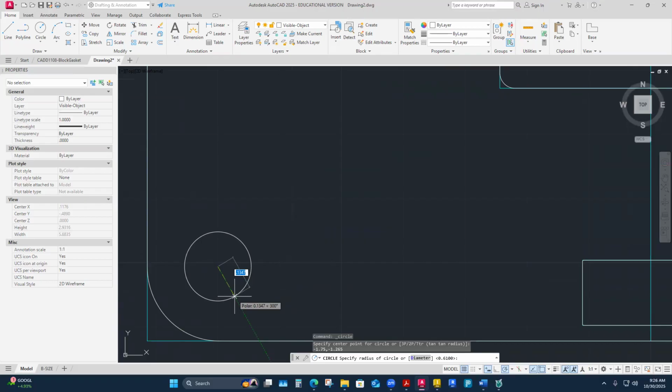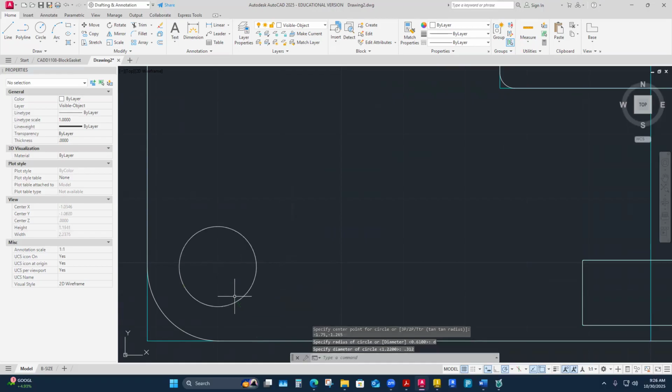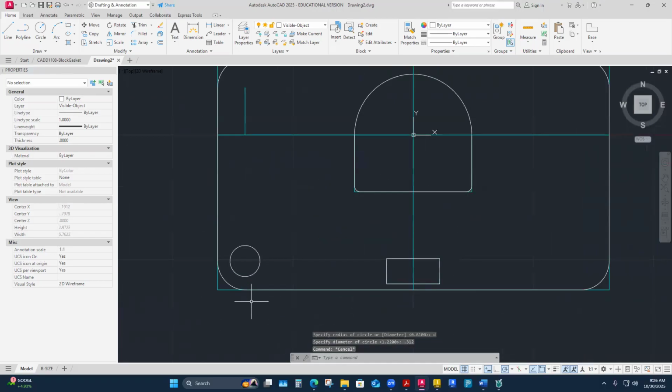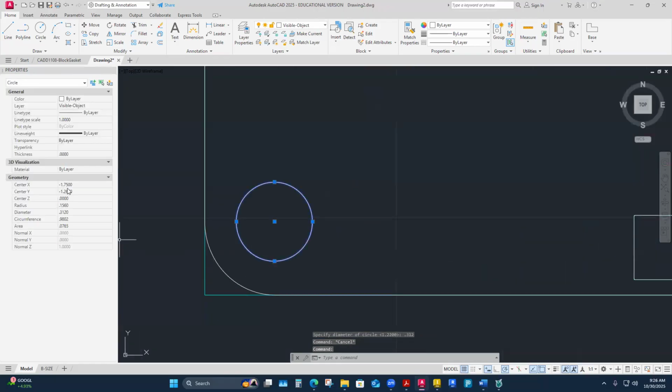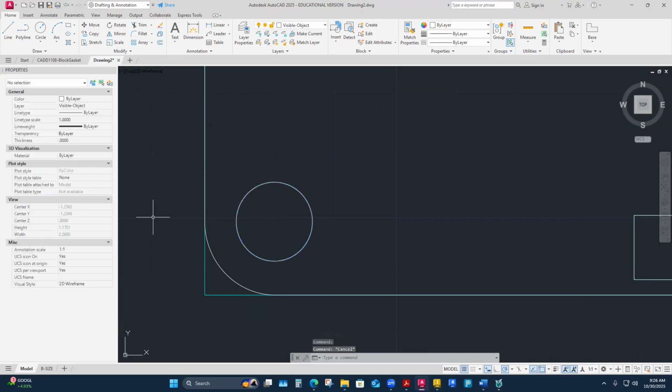So this is how I located this. And then these ones are diameters, so I can hit D for diameter and say it's 0.312. There's really no construction material around it, but I can always select it and see its coordinate values right here, X and Y. These should match my dimensions. Isn't that killer? That's going to be the way I do this for sure.